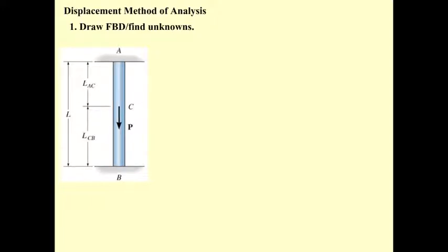This is the axial load structure, a statically indeterminate axially loaded column. Under the load P, this one is going to have the reactions. This is going to be F sub B, this is going to be F sub A. And since the force is axially loaded, that means it's passing through the centroid of the section. So the summation of F sub X is 0.